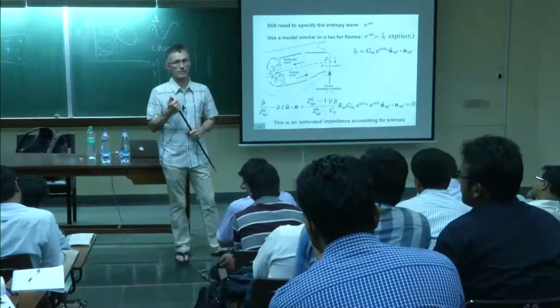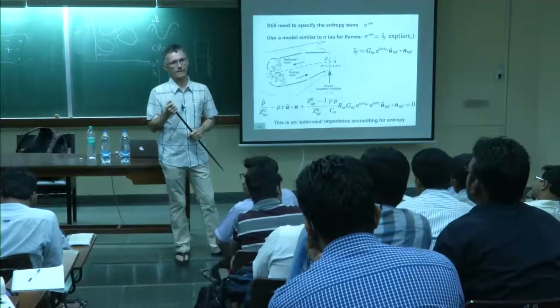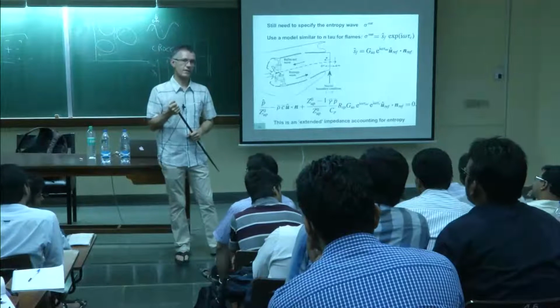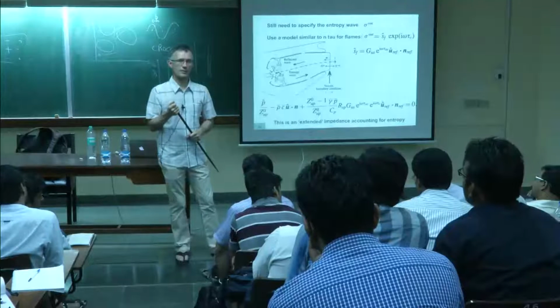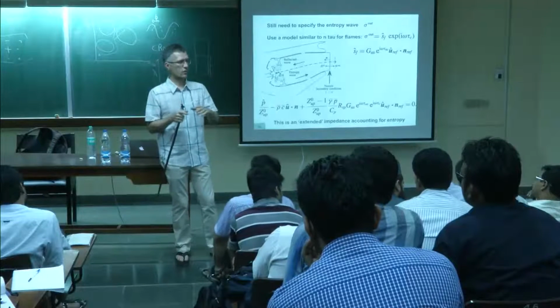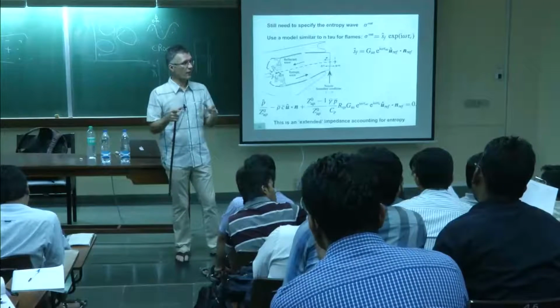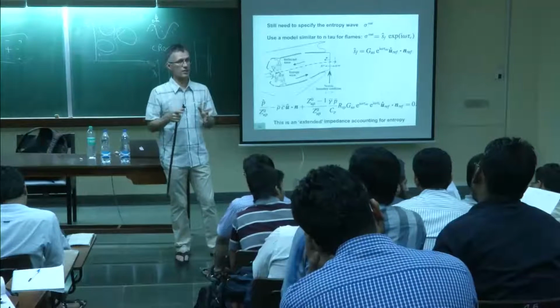Sir, how to separate the standing mode from the rotating mode in the case of the transverse mode? That's the big question, yeah. For the moment, it's difficult. The first thing you need to do is to compute all these modes. You need to know all the acoustic modes of the rocket engine. After that, to know which one is excited is extremely difficult.